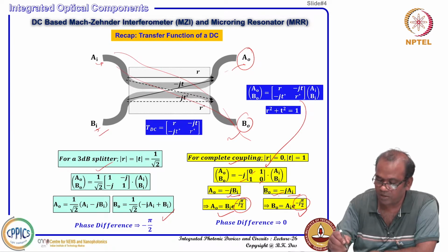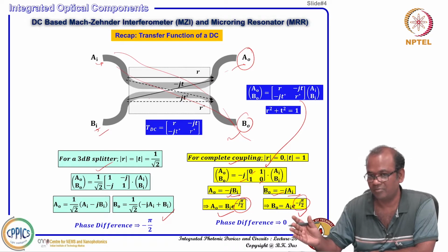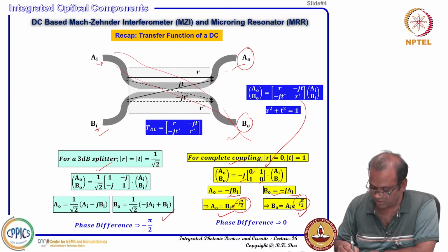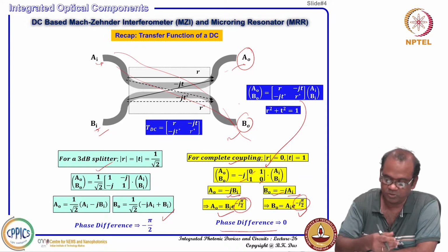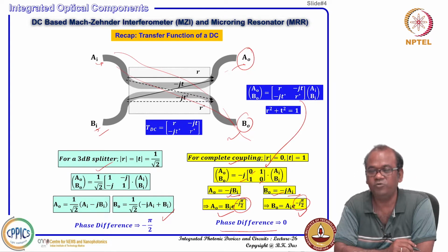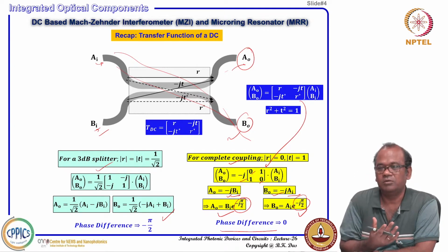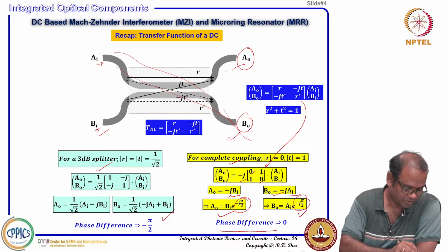So, they do not have an additional phase difference because of the directional coupler, but both are having some kind of phase, an identical phase. That is why the directional coupler in this type of situation does not introduce any phase difference between these two output ports, because we are considering both input and both output. Good. So, this is the directional coupler, all we need to know to construct more advanced complex photonic integrated circuits or integrated optical circuits.